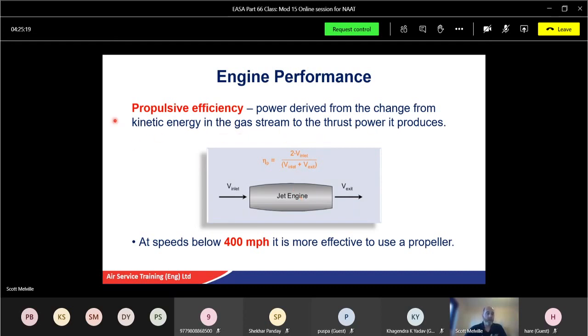There's also some waste from the propelling mechanism, as much is dissipated into the exhaust gas stream. So at lower speeds, the pure jet stream wastes a lot more energy than a propeller because of the higher exit velocities. As aircraft speed increases, you get a better ram effect, as I said before, so we can match the force going through the engine to the surrounding air.